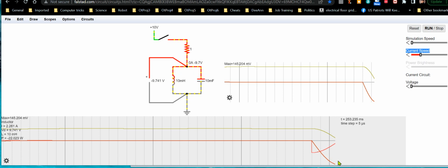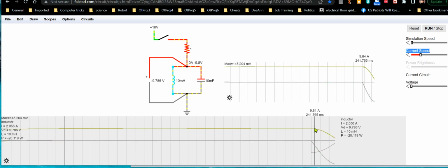But again, the capacitor can't lose any energy while this is happening, because the inductor is generating a slightly higher voltage across the capacitor than it has at any one point in time. So instead of the capacitor losing energy, it's gaining energy, and only gaining energy. The only thing that's losing energy is the inductor during this first quarter cycle. Because what happens here, and you're going to see this in a second,